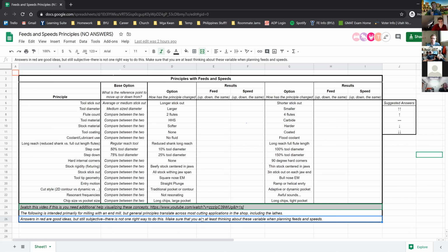Routers tend to be less rigid, and things tend to be a little more shaky on the tip. So routers tend to do shallow depth of cut and feed really fast. For reference, when Alex Laraway was doing aluminum on the ShopBot, he was doing 40 thou depth of cut, but feeding at 200 inches per minute. So you tickle it and you cook fast.